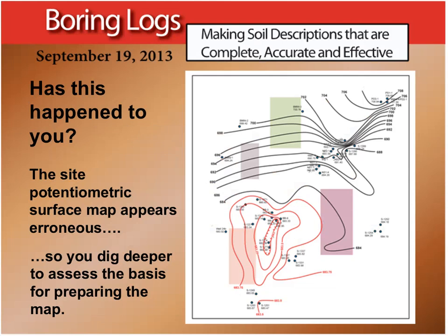Here's an example. Have you ever inherited a project where your intuition tells you there's something wrong, maybe with the potentiometric surface map, or possibly your upgrading water samples appear to be measuring downgrading impacts? Or have you had difficulty correlating buried sand units when you design a groundwater monitoring system, or understanding the physical properties in the subsurface, specifically understanding the distribution of hydraulic conductivity under your site?